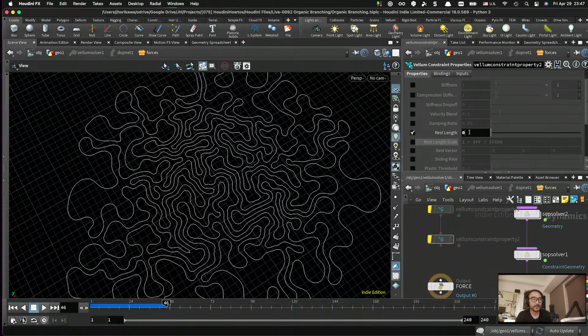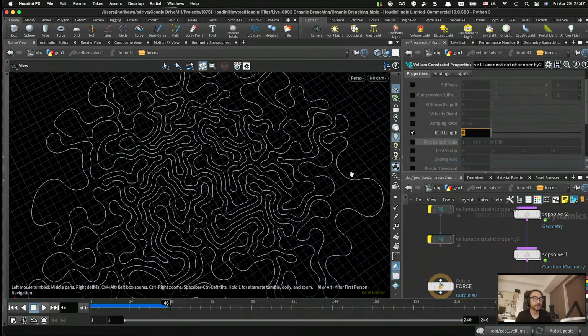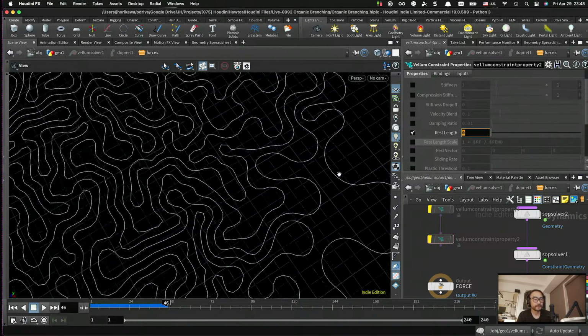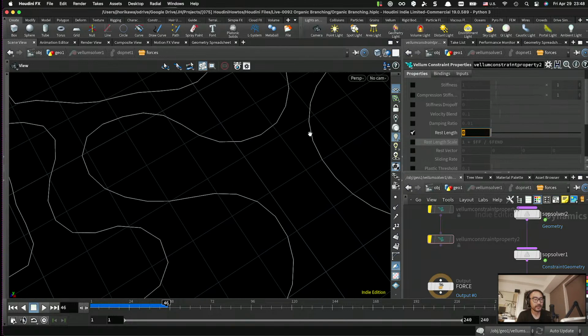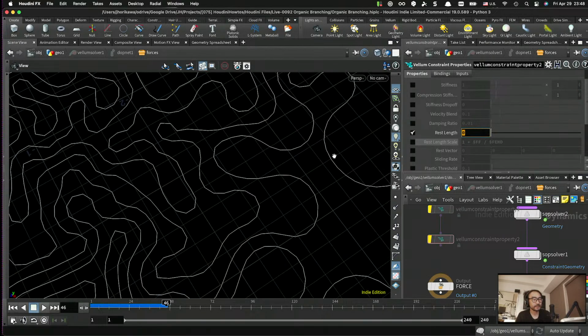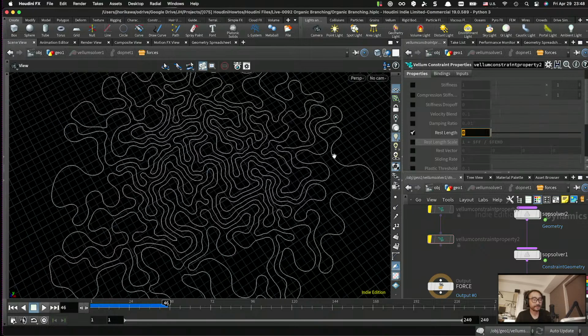By keeping the value equal to 0, it's going to try to keep the angle between the curve flat, to make the angle between two edges flat. If you make it 90 degrees, then it's going to try to make the angle between the curve perpendicular. So keep that in mind.